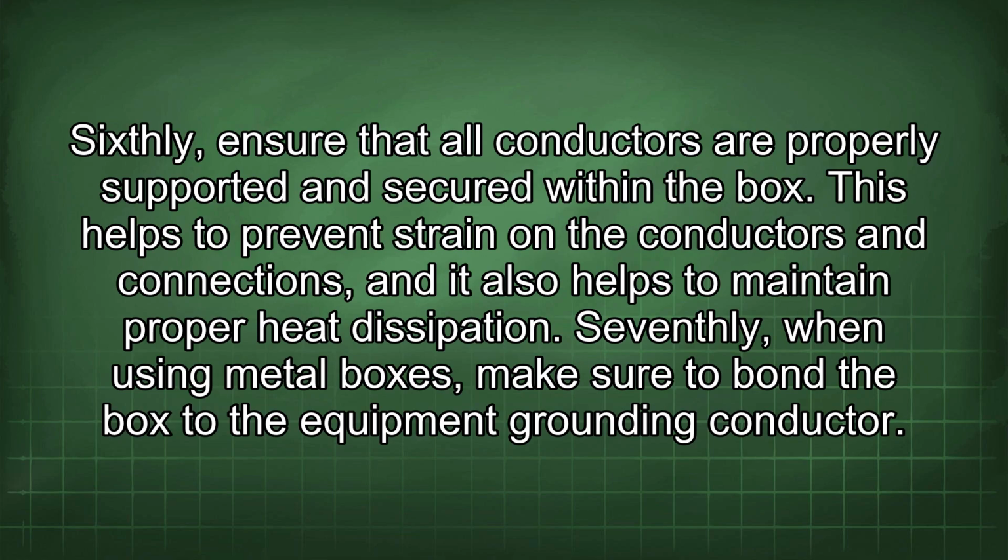Sixthly, ensure that all conductors are properly supported and secured within the box. This helps to prevent strain on the conductors and connections, and it also helps to maintain proper heat dissipation. Seventhly, when using metal boxes, make sure to bond the box to the equipment grounding conductor.